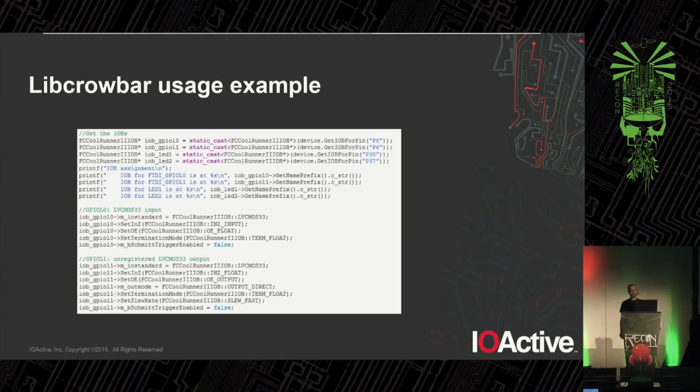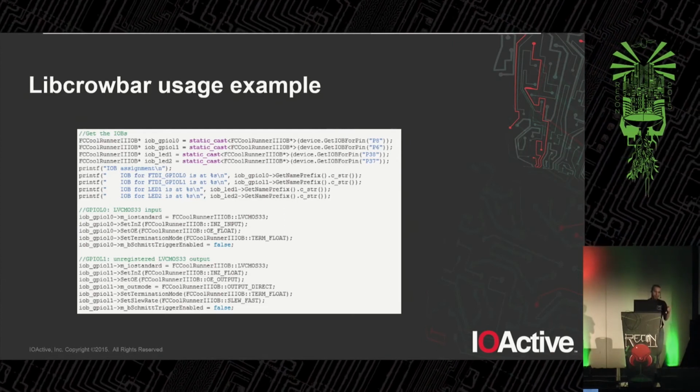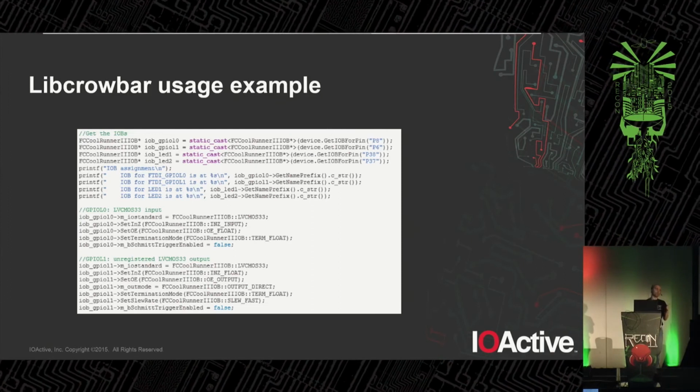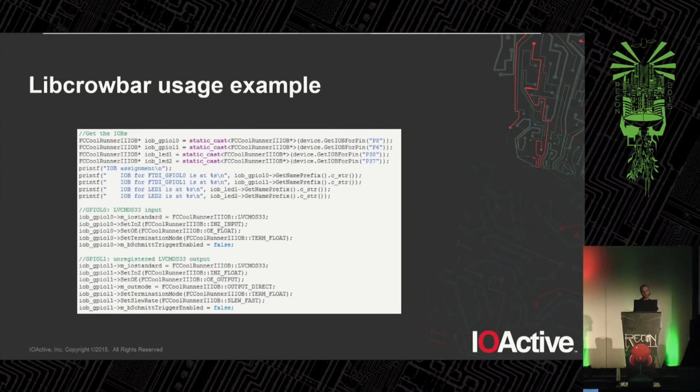I can also go the other way around. I can go from a programmed device, I can read out the bitstream. I can turn it into an ASCII art schematic, and I can turn it into synthesizable Verilog, as long as you're not using the features I haven't yet reversed the functionality of.